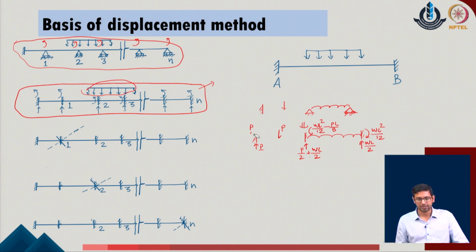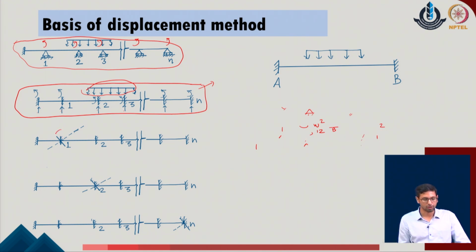As a next step, we understand that the given kinematically determinate system is not the same as the original system. So, what we do is consider the given problem with respect to the first case of deformation which is available over here. If this amount of deformation is theta 1 in the given node, we provide a unit amount of theta 1 in this condition.